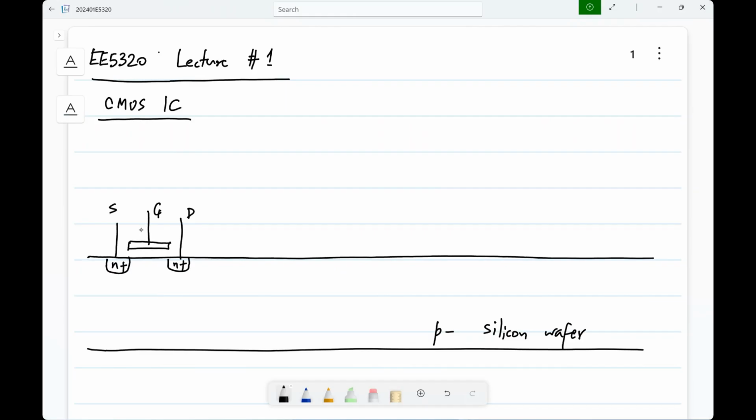Now, one thing that will also be different from the MOS model you learned earlier is that very likely the MOS model you saw had only 3 terminals, but in reality it has a 4th terminal, which is the bulk. Again, you would have seen this, but there is something special about the bulk here. The silicon wafer itself is the bulk connection. So if you have multiple transistors, the same bulk is present for all of them. That means that the bulks of all the transistors are connected together. So that is one thing different about an IC than discrete circuits.